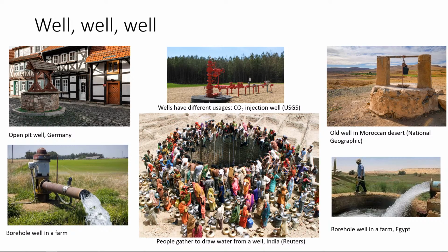What other application? Remember we talked about dam failure briefly. One thing is, if you are worried about the structural integrity of your dam and that it will not overturn, one remediation measure or one way to fix this is to relieve pressure from under the dam by pumping the water out. If you have excessive groundwater under the dam, you can relieve this pressure by pumping it.